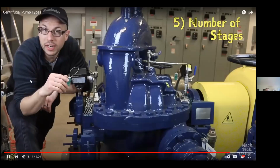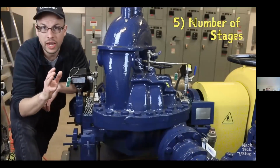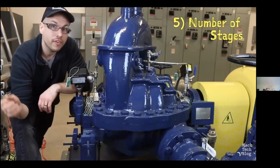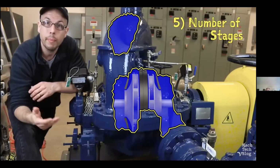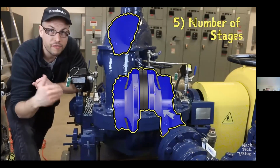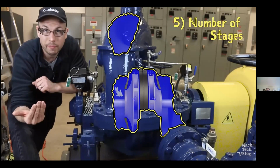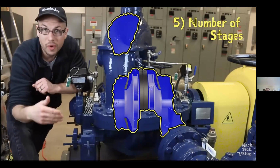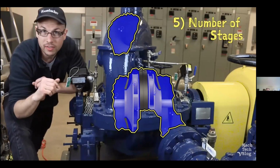Finally, a pump can be classified by how many stages it has. Most pumps have one stage with a single impeller and a single volute chamber. However, some pumps have additional stages connected in series to help boost the pump's discharge pressure. The idea is that the first impeller adds energy to the fluid and then feeds it into the next impeller, which adds more energy to the fluid, then feeds it to the next impeller, and so on and so forth until the fluid is eventually discharged into the system.